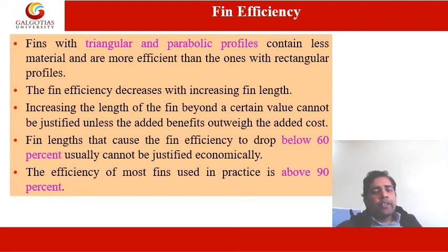Then again, the fin efficiency decreases with increasing fin length. As we increase the length of the fin, the efficiency, as you can see, is a ratio of actual versus ideal heat transfer. So the ideal heat transfer rate increases, and this actually results in a decrease in the fin efficiency.